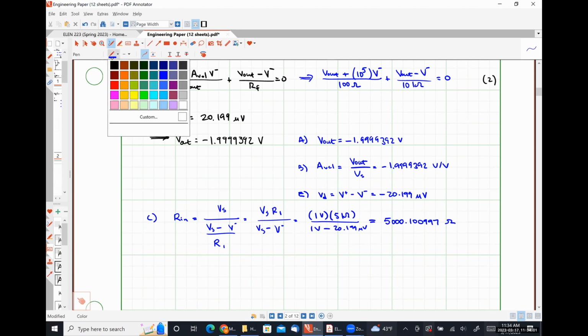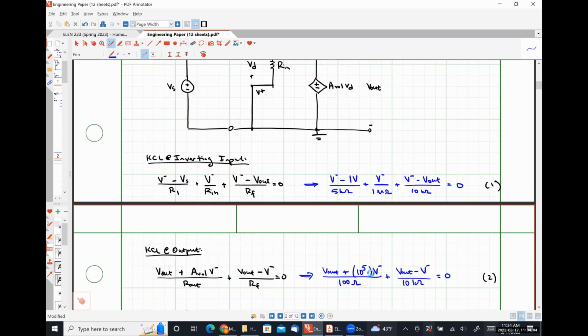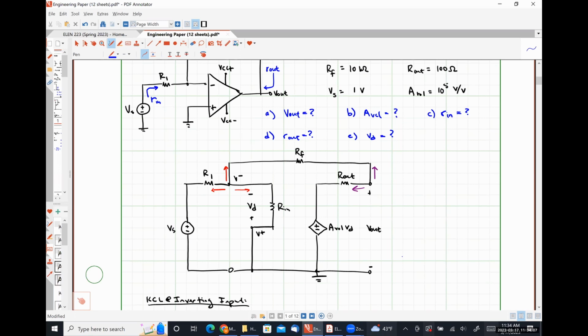To calculate our output resistance, let's look at things we have here. So to calculate our output resistance, we are going to apply a test source. Actually, that's one way to do it. One way to do it would be to apply a test source to the output terminals of our dead network and then find the Thevenin resistance. But we could also find the Thevenin resistance by determining the open circuit voltage and the short circuit current there, right? I'm going to use that second method because we already figured out what the open circuit voltage was, because this is an open circuit.